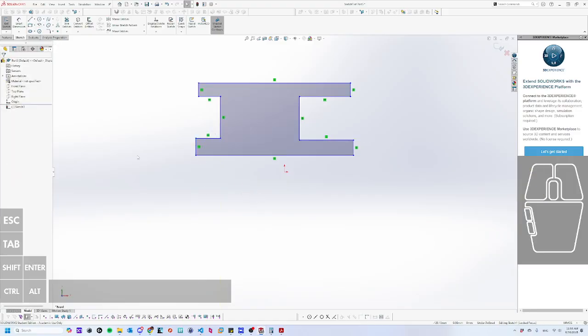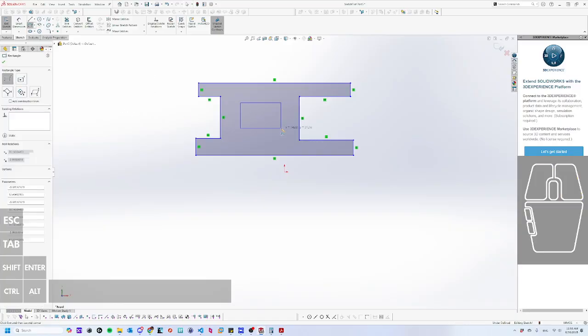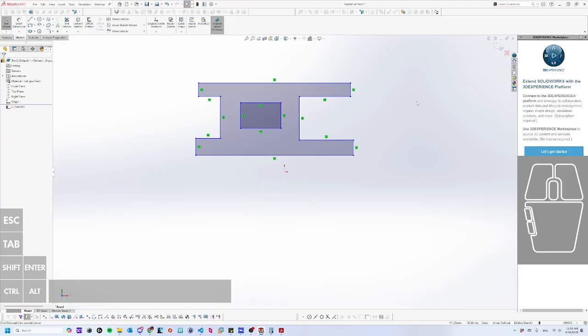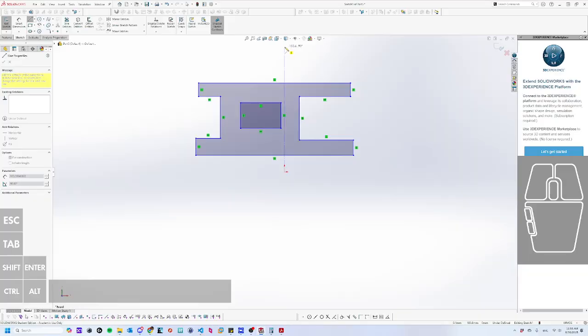And then it had a rectangle in the middle, so I'm going to select the rectangle tool, right click, drag downwards, and then I can quickly sketch a rectangle. Let's start off by adding a center line because it's always useful, and I can already tell that this part should be symmetrical. I just want a vertical line, which you can see next to the pencil has popped up as the yellow vertical icon whenever it's going to add the vertical constraint to this line.